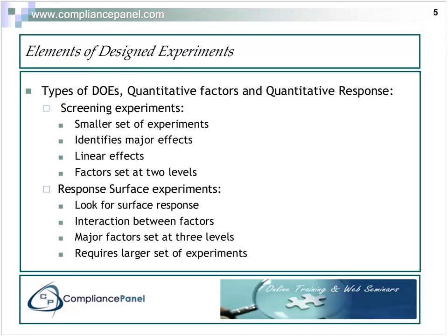So I'm going to have a low dwell time and a high dwell time, a low pressure and a high pressure, and the same for temperature. So we have each of the factors at the two levels. So that is a typical screening experiment.